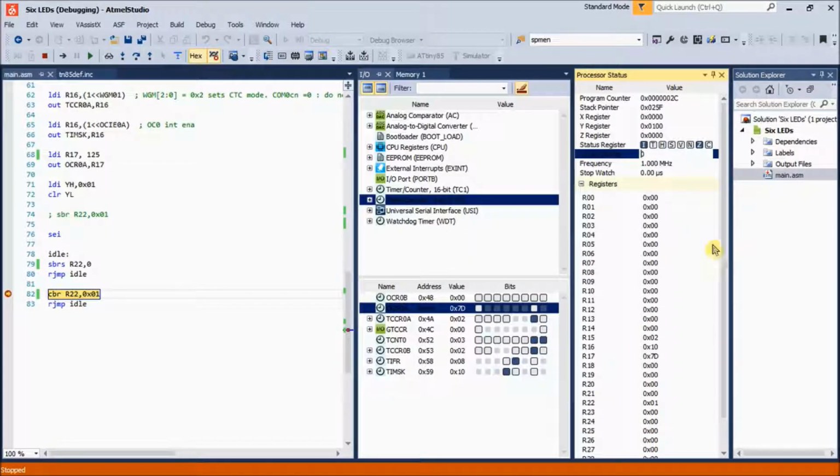Right, I'm back again. Now, if we set a breakpoint here, so if I execute F5, it's gone to the breakpoint. I have reset the cycle counter here. I've reset the stopwatch. If I press F5 again, it should get back here again in 1000 milliseconds, right?